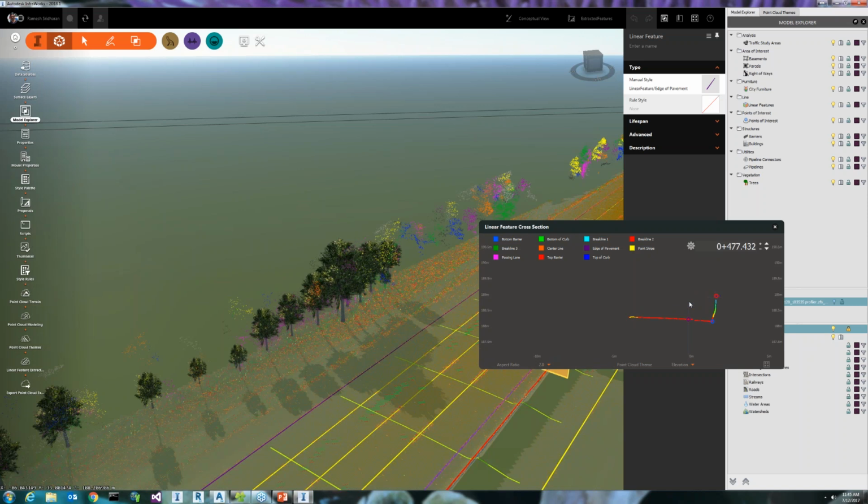The automation right now is focusing on roads, but the cross section is a little bit open. It lets you extract pretty much whatever you see in the point cloud. I think one of the customers did a bridge, the columns and things like that. When they go through the bridge, they want more details, so they can extract a 3D polyline.